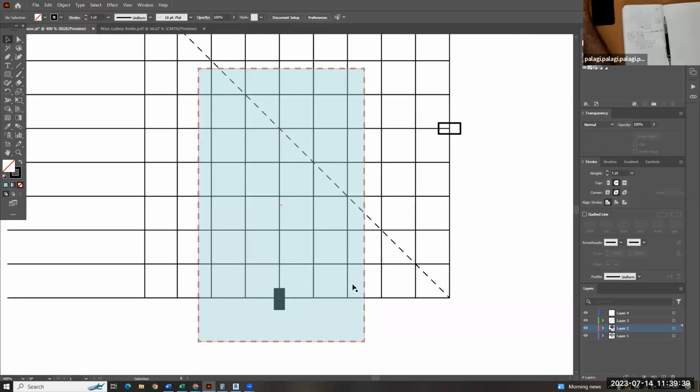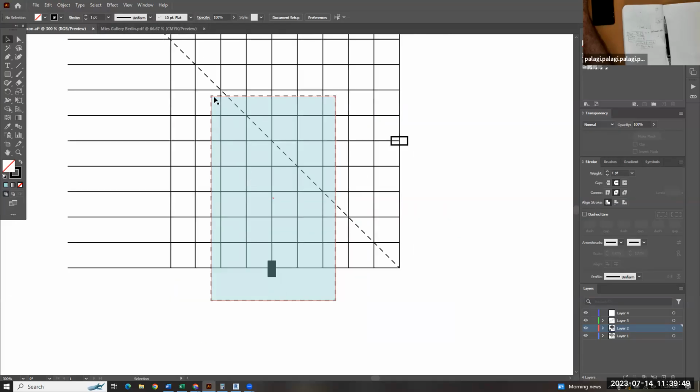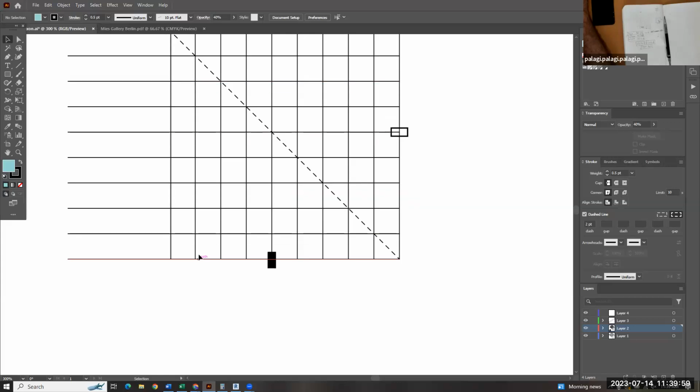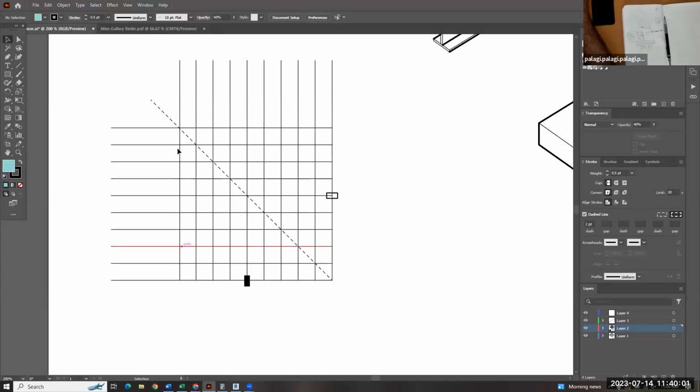So does each one of these coming to hit this drop the same amount of load on this beam? If this is the trib area... no, exactly. Each one of these is bringing way more weight, right? That's what I was saying. What's interesting here is that the middle ones are carrying way more weight because these are self-supporting. This one's only really going, you know, in fact, it's transferring load. So the idea that more and more weight is coming on there is kind of an interesting thing